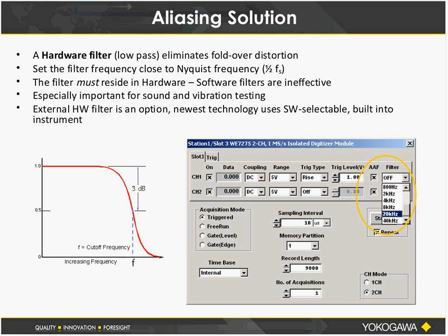It's essentially a hardware filter that is going to preserve the phase characteristics of your signal and provide a very steep roll-off, and allow you to also set a user-definable filter frequency that's going to be related to your sample rate and indirectly related to that Nyquist fold-over frequency. So a hardware filter is, for better or worse, the only real solution to dealing with this aliasing problem.